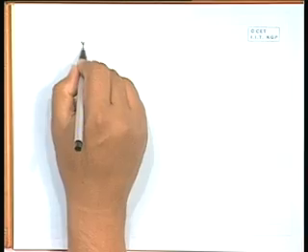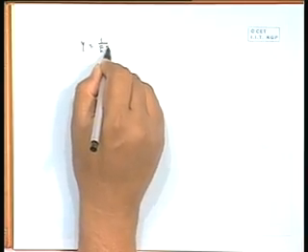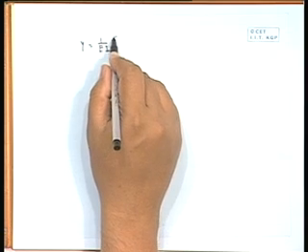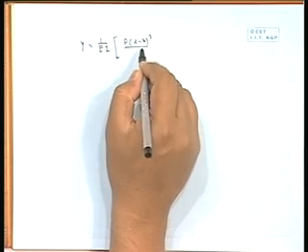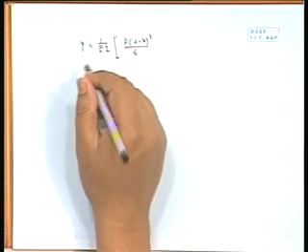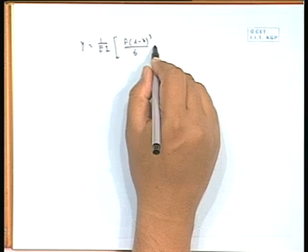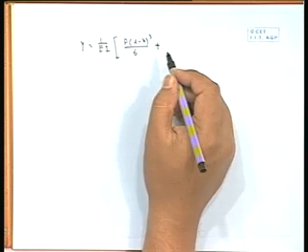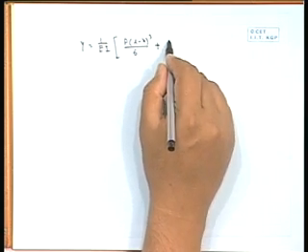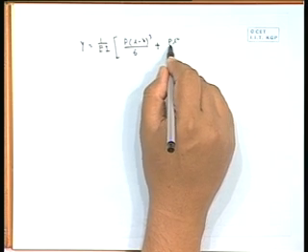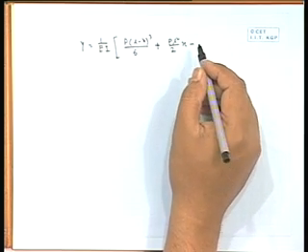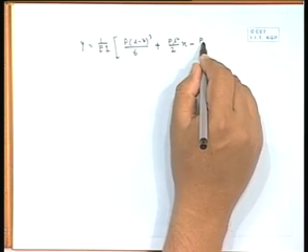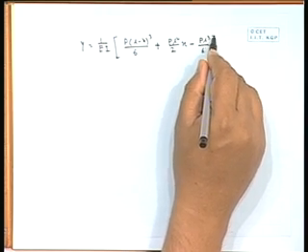So, it will be y equal to 1 by EI, and here we got P (L minus x) cube divided by 6 plus, C1 we got P L square divided by 2 into x, and C2 we got P L cube divided by 6.